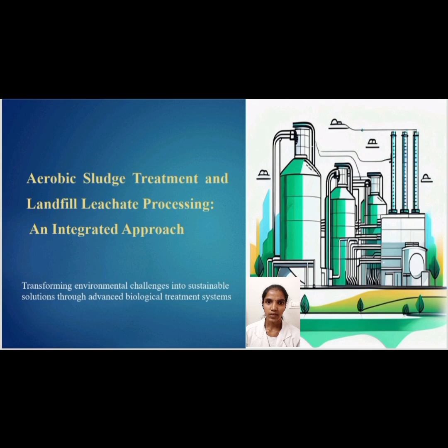The topic is that we are learning how to clean wastewaters. There are two major types. Type 1, sludge, the leftover solid waste from the treatment plants. Type 2, landfill leachate, the dirty liquids that come up from landfills. The goal is to understand how aerobic treatment, which means the oxygen-based biological process, helps clean this waste.